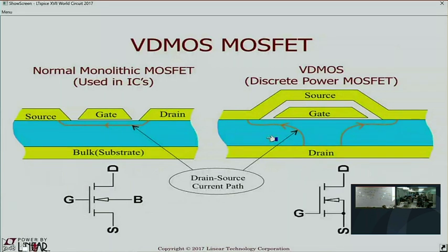When you take a power MOSFET and solder it to your PC board, it's a 10-meter wide transistor. See, that's a small area. Half a micron by 10 meters. You could put that in a few millimeter square die, and you could put 6 of them inside of a TO220 package, and they'd rattle around. But you're really dealing with a transistor that's 10 meters wide and half a micron long.